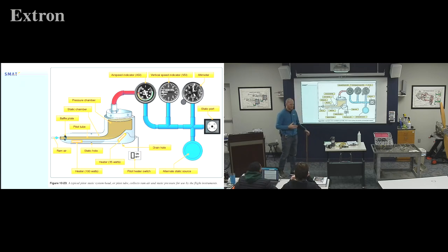Yeah, so there's different ways to do it. You can check amp draws, you can do stuff, but is it working? Click it on and see where we're at. You may want to find the manual to see if it has specific ways. This one you notice has 2 heaters in it. Maybe only one heater is working out of the 2, but if he asks, hey, is the pitot tube working? You might want to clarify and say, am I just checking like a pilot checks? Yes, is it working? Or do you want me to confirm based on the manual? And he says, well, the manual. Oh, okay. Grab the manual and see what it says, right? So, pitot tube has heaters, has a drain hole, connected up to our airspeed indicator.